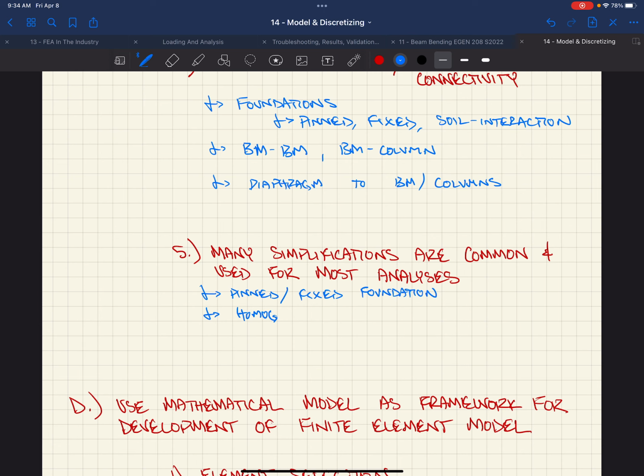Even with some really deeply drilled things, would you still assume a fixed? You can still assume a fixed. I'm saying, would that be more accurate if you do some really deep drill? It depends on the stiffness of the soil itself. If you have something really deep, you might gain some stiffness, but if you're going really deep in, say, a clay, then you've got this big, tall pile, and when it tries to deflect, it's got clay to resist it. And so it's still not going to be as stiff as maybe a 4 foot deep, thick spread footing